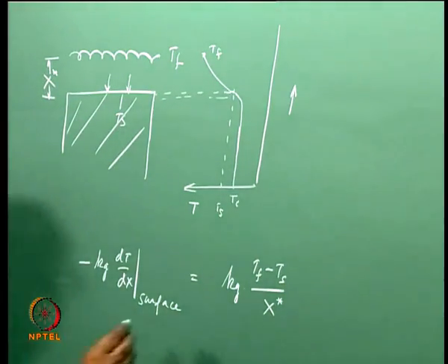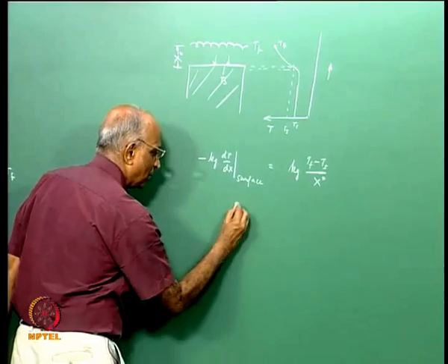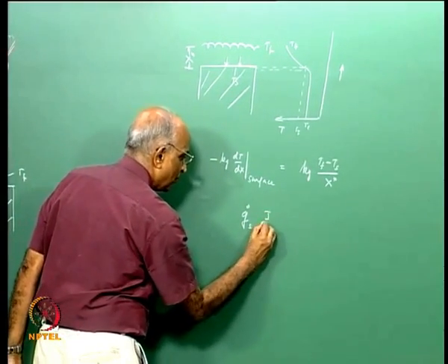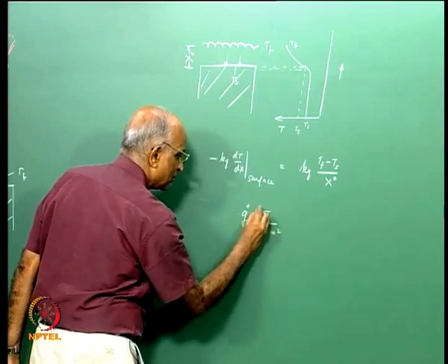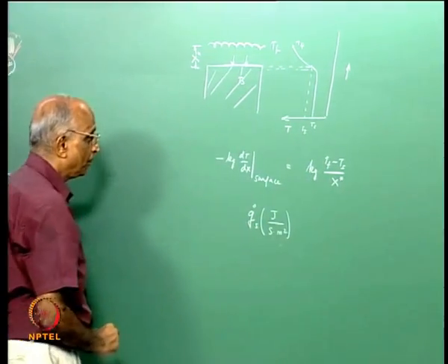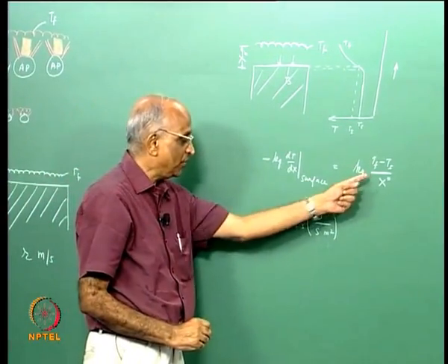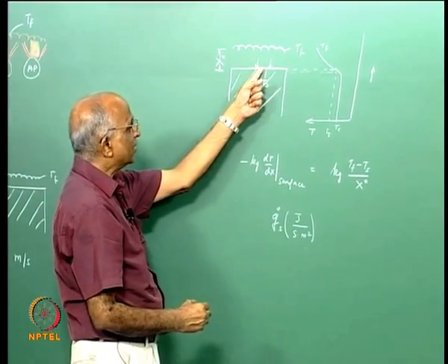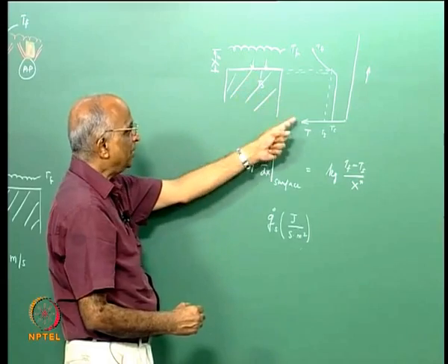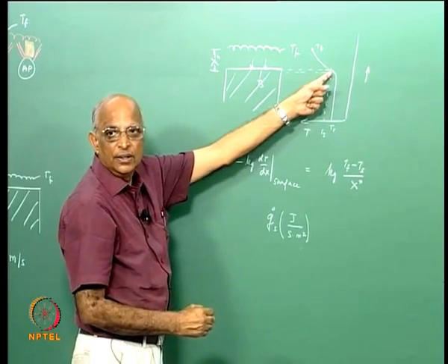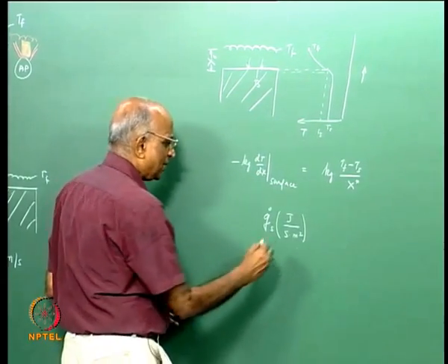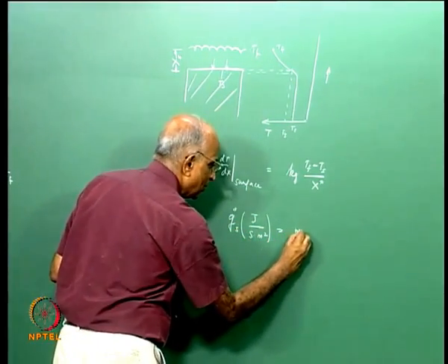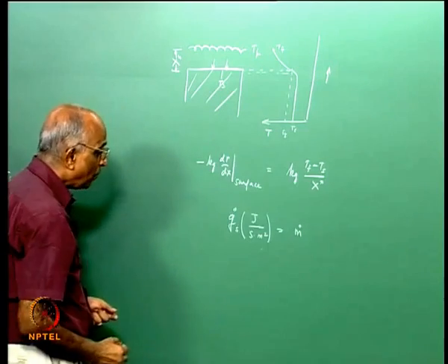Well, this is the heat which is coming to the surface. I say this is equal to Q dot S. I consider unit surface area, therefore it is so many joules per second per meter square. Mind you, A is unit surface area, and where does the heat go? The heat goes to increase the surface temperature from the initial value Ti to the Ts value. Let us say that the rate at which the propellant regresses or burns is equal to m dot.